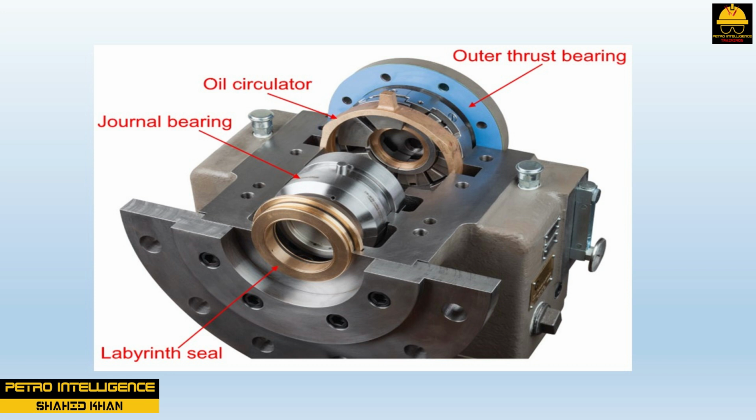Oil supply passages are built into the radial housing, or a slinger ring lubricates the bearings. As the shaft rotates, the lubrication forms a thin film between the shaft and the bearing that allows the system to float. This type of bearing typically is located beside the thrust bearing on one end of the turbine and by the shaft seal on the other.